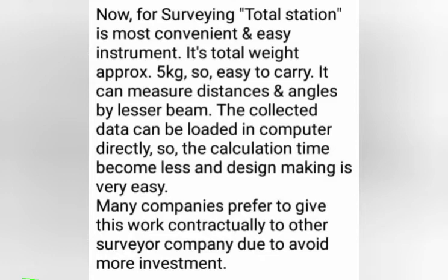It is simple to set up with the application of laser plummets. It has four components: EDM (electronic distance measurement), electronic theodolite, microprocessor, and electronic display.